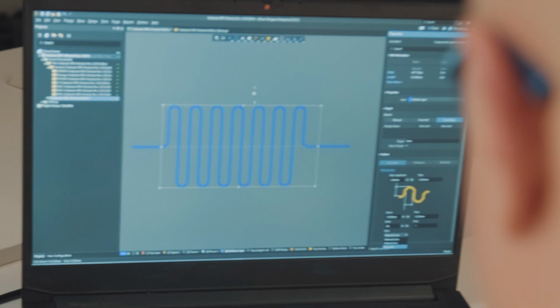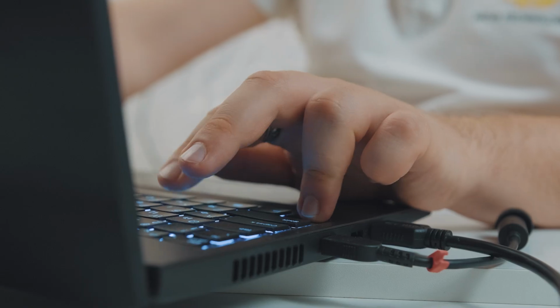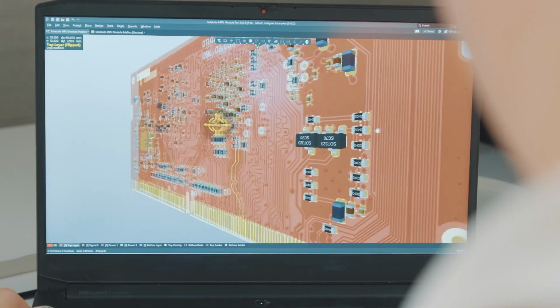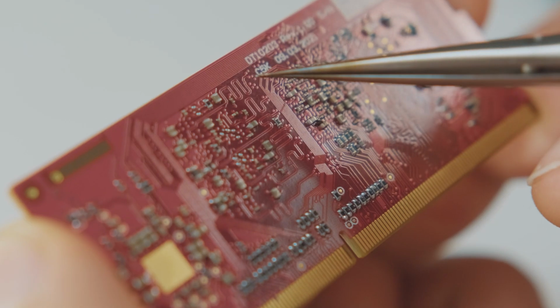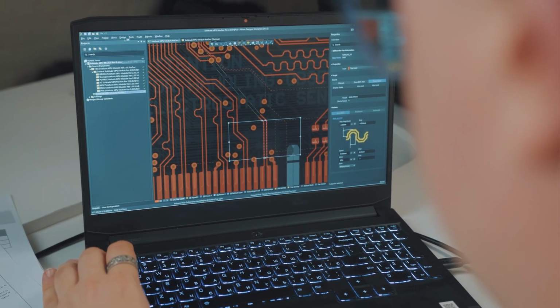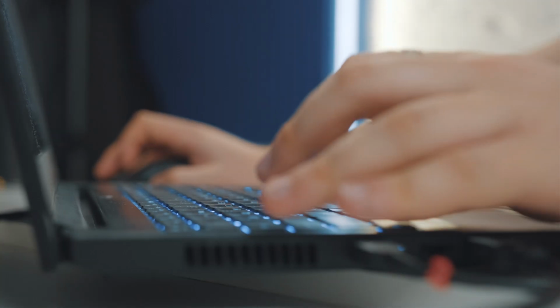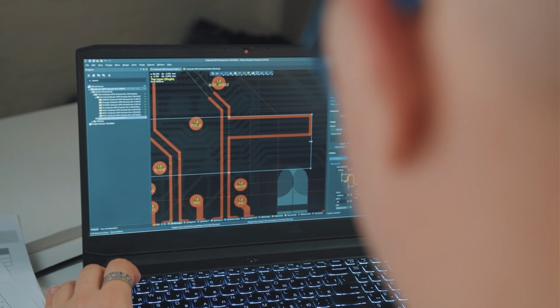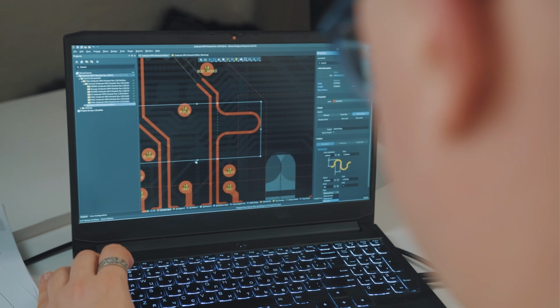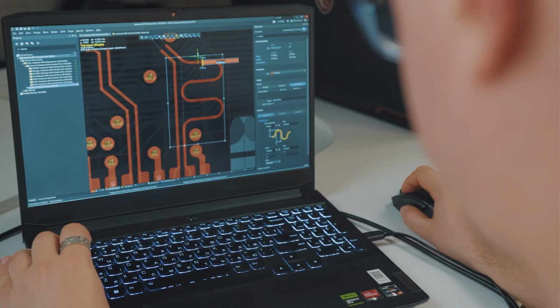Rounded corners help improve signal integrity by reducing reflections and EMI, especially important for high-speed RF circuits. They also reduce mechanical stress during manufacturing, making the board more reliable. At the same time, the lengths of parallel lines must be matched. The signals should arrive without delay difference between each other. Let's use Altium Designer and set up rounding lines.